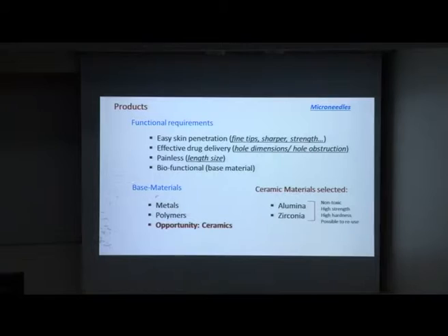Which are the functional requirements we need in this kind of things? First, skin penetration. For that we need fine tips, we need sharpness, and we need high strength. We need effective drug delivery. In this case the hole dimensions are important, and it is important to avoid hole obstruction of the microneedles. We need a painless design, so the length should not be higher than 1.5 millimeters. And we need a biofunctional base material, at least non-toxic for the body.